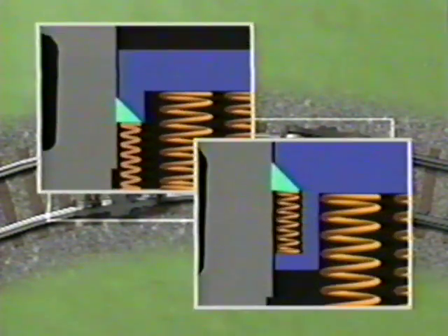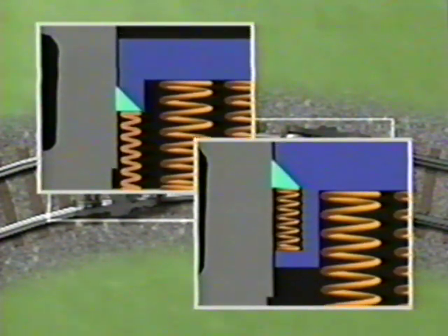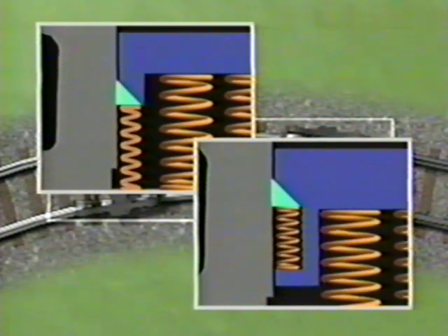Earlier, we learned that several factors affect a truck's resistance to warping. First, a significant part of a truck's warp restraint comes from the snubbing wedges. Snubbing wedges, which slide easily, lower a truck's warp resistance. Factors which decrease snubbing wedge pressure include wedge wear and snubbing spring damage or fatigue.